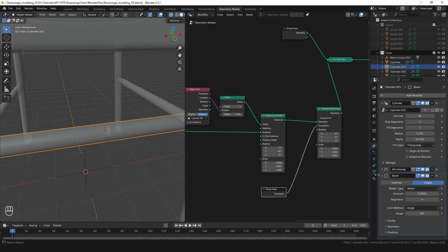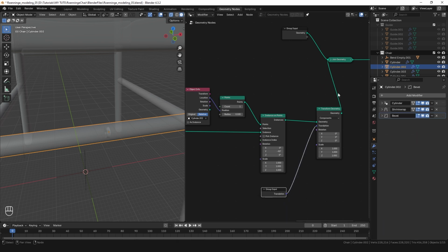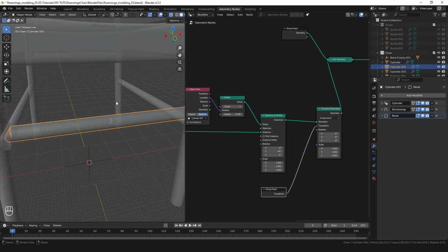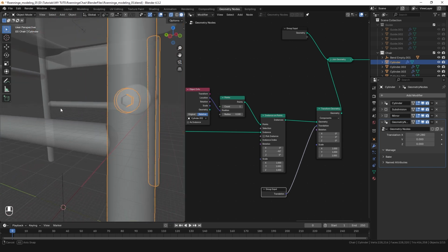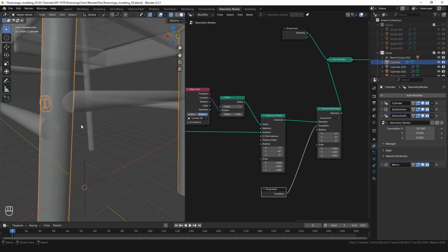We still have the stretcher cylinder selected, but we've been editing the pin geometry nodes of the leg. So let's select the leg object to edit its modifier. And here is the translation we've exposed. Let's edit the X value to position it where needed. And we need it before the mirror modifier.